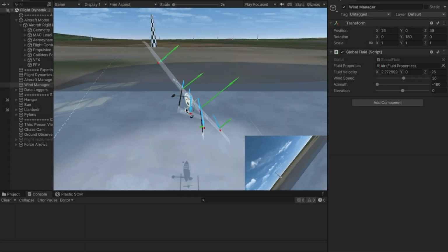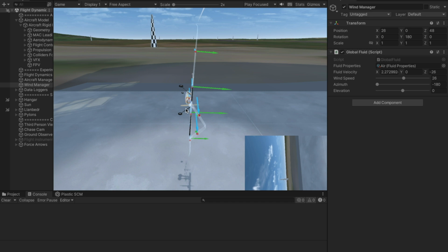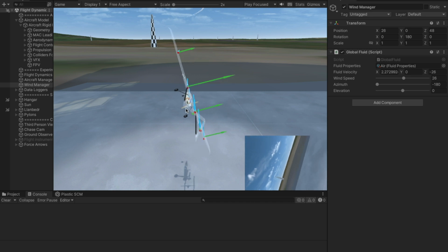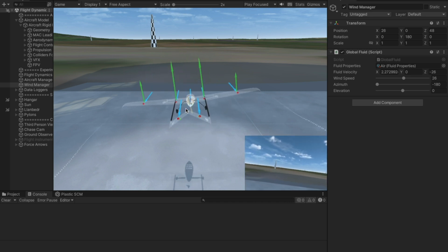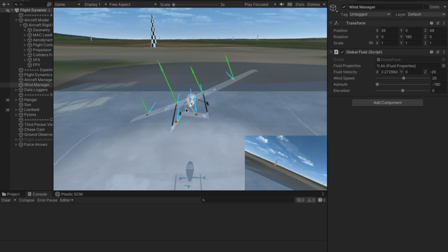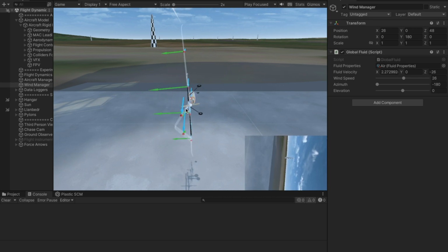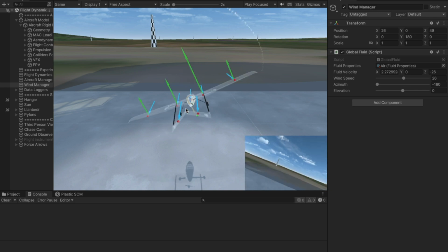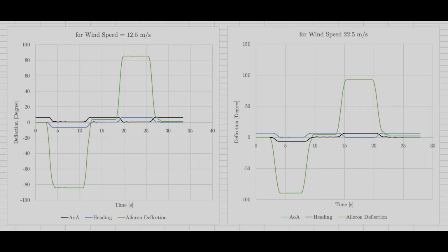The aircraft's rolling characteristics were then modeled and evaluated using lateral dynamic response tests. These tests were conducted to determine how rising wind speed influenced the aircraft's roll rate for a fixed aileron input, and to confirm that the proper rudder input resulted in the proper corresponding angle of sideslip for the aircraft. Finally, the damping in pitch and yaw were contrasted.